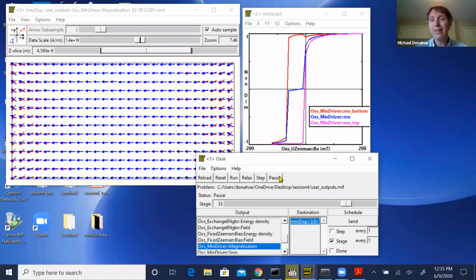Because of some details on the way that the spins are normalized to keep them on the unit sphere, it turns out that the RK4 sort of artificially adds in a little bit extra damping. And so if you're running in a low damping regime and it goes unstable, using RK4 tends to be more stable. There's also a couple RK2 methods. I don't know any particular reason to use them, but for comparison to other simulations you find in the literature that might be useful.